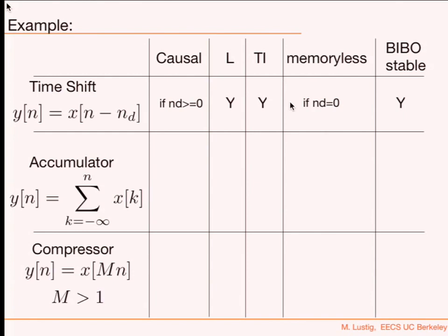Is it memoryless? Only if the output is exactly the input, then there's no need for storage. But otherwise, there has to be some storage, so it's not necessarily memoryless. And the question is, is it stable? BIBO stable? And yes, of course it is BIBO stable.